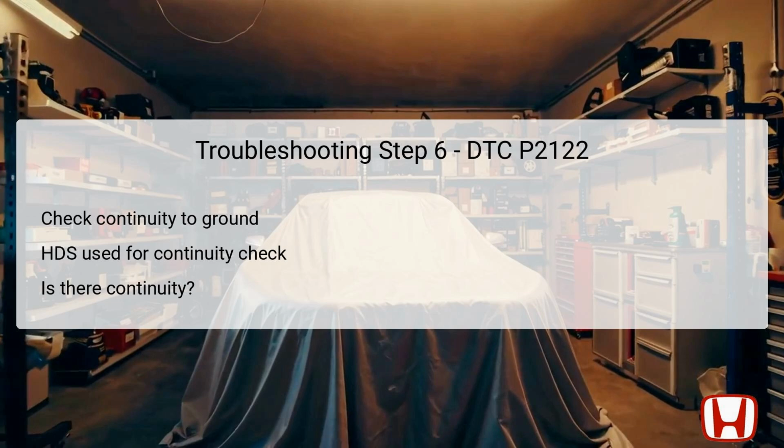If continuity is confirmed, it illustrates that the wire and connections are functioning correctly. However, if there is no continuity detected, this suggests a break in the wire or poor connections that require immediate attention, leading the technician to the next step in the diagnostic process.